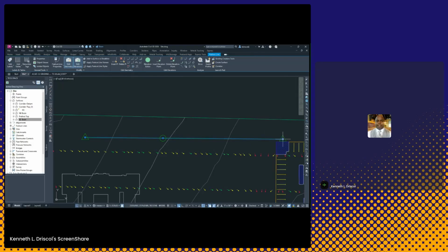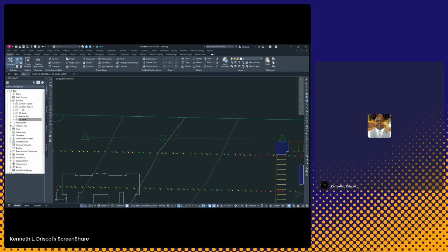And if I pick on this and lengthen it, it's just giving me information without me having to say rise over run to determine a slope or a grade. And this is why I use feature lines. I can come in and make reference. I'm so much more efficient in terms of the things that I'm thinking in my head. Okay. Feature lines. There's a lot we can do with feature lines.